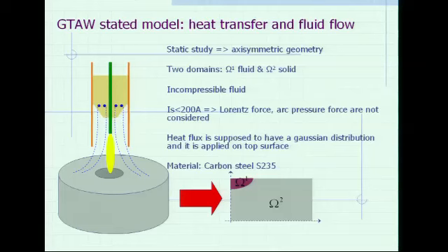We are doing a static test welding, not a real one like in the industry, not two plates welded together, because it is too complex to study. We have a contact between two plates, and we cannot. So it is a cylinder, and you have a torch on the top, and we are heating this cylinder to create this weld pool shape. We decided to work in axisymmetric geometry, so it simplifies the model, and also reduces computing time.